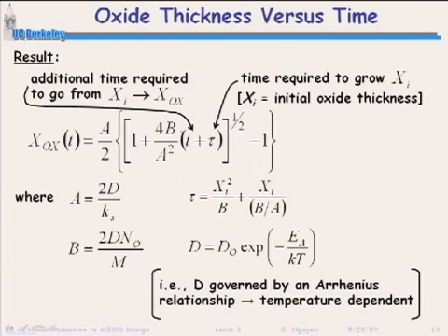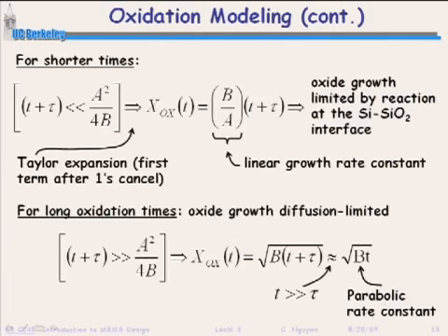And we call the linear growth rate constant the constant associated with the linear part of the growth, and the square root B the parabolic rate constant. Okay? And you have constants for all of these different things. So these are constants for that diffusion coefficient. So that E1 is the activation energy in the Arrhenius relationship. The C1 is the same as D naught that I had in the previous slide.